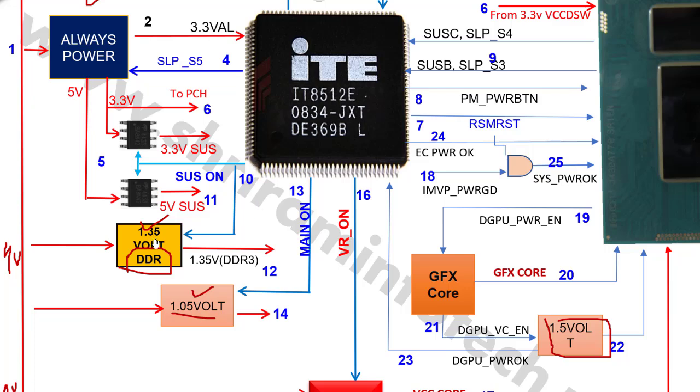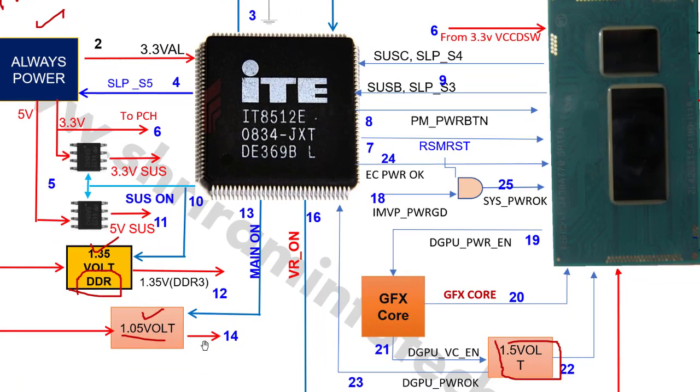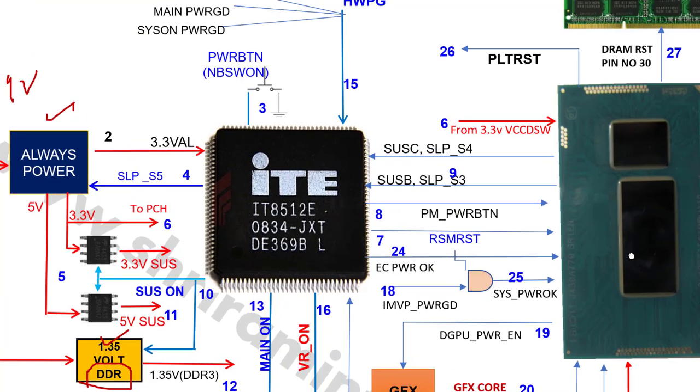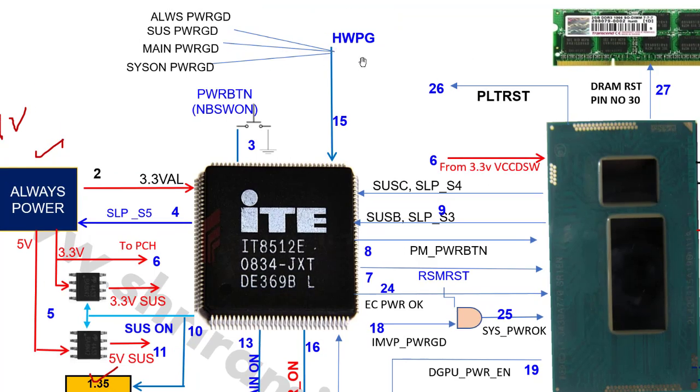Then the next signal will be the step number 13 MAIN ON signal. The MAIN ON signal will turn on 1.05 voltage, and after that 1.05 voltage is generated, and this voltage is also going to the CPU. Okay, then see, here is one signal called HWPG. HWPG is hardware PG, that means the power good signal.